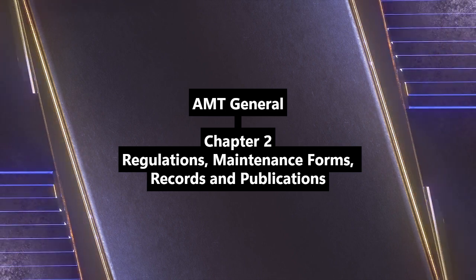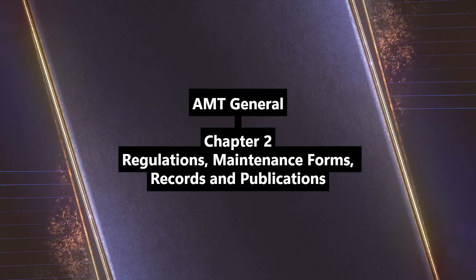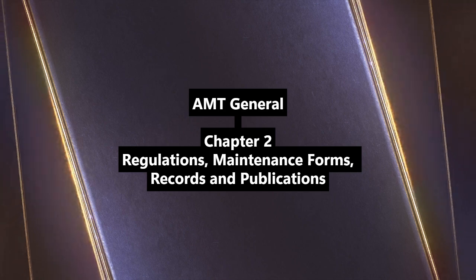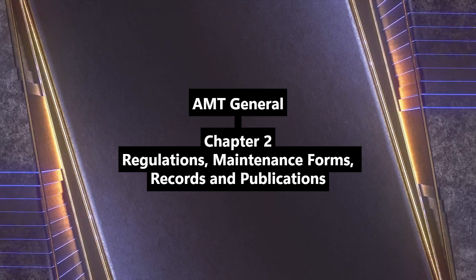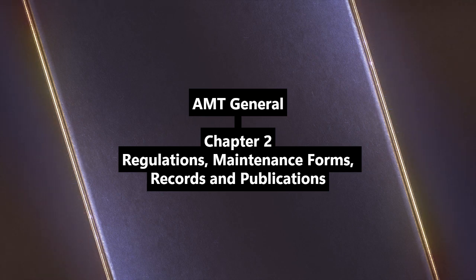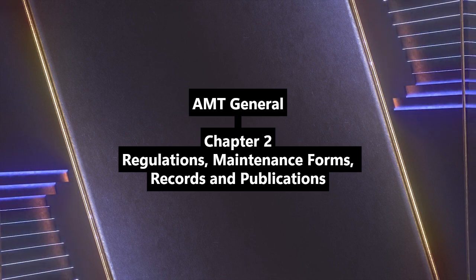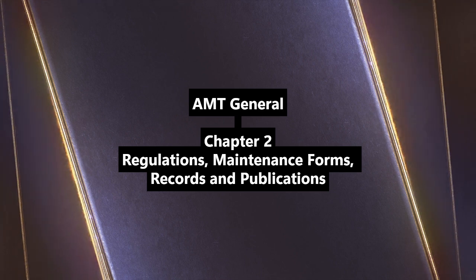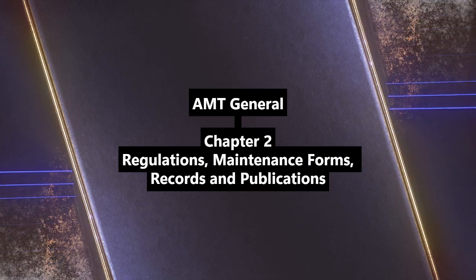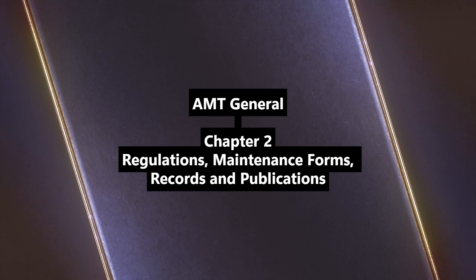Okay. Section 43.11, records for inspections. How is this different from 43.9? Similar what, when, who requirements: type of inspection, date, and total time in service, signature, certificate details of the person approving or disapproving return to service. Disapproving, what happens then? If an inspection finds issues making the aircraft unairworthy, the inspector disapproves it, gives the owner a list of discrepancies, and the log entry must reference that list.